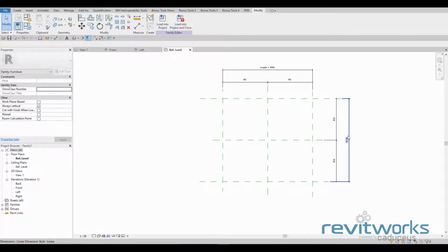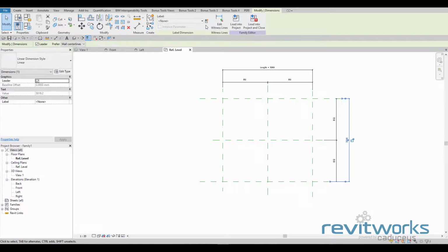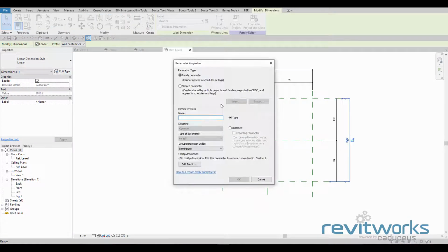And we'll do the same for this one. We're going to create this to be the width. So again, create a parameter, call it width. Capital W-I-D-T-H. Now, it doesn't actually matter how you spell that or create it or what case you use, but you do want to lock in on a consistent formatting. Like I say, my consistent formatting is always a capital W and then lowercase for the rest of it.